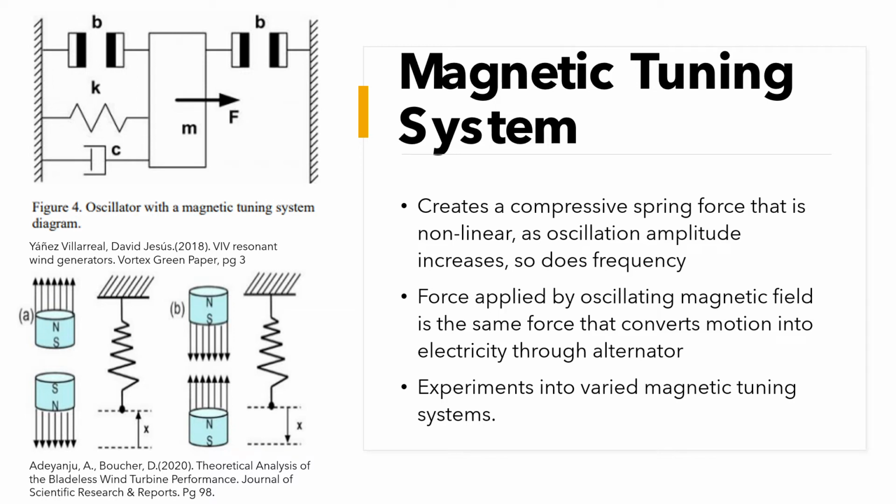One recent study was conducted to investigate the implementation of both similarly and oppositely poled magnets to be used in combination to even further enhance the lock-in zones and power generation by increasing the spring force, as seen in the bottom picture.